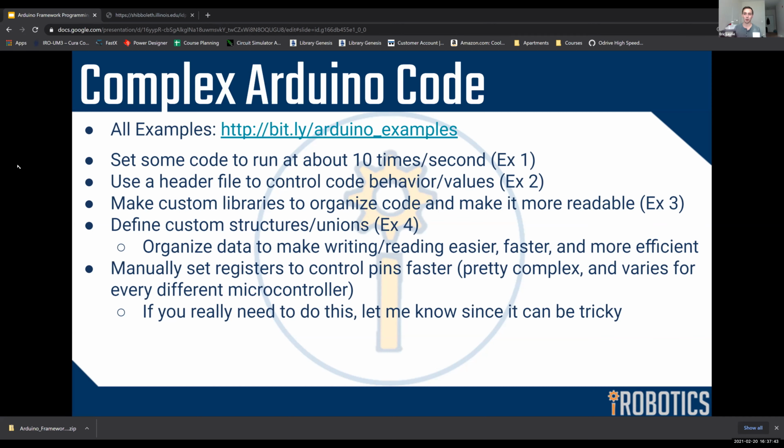They don't run at gigahertz like the CPU in your computer. Super fast ones run at like 400 megahertz. I think Arduinos run at like 8 megahertz; the Arduino Nano, Uno and Mega run really slowly. So the more things you can have happen slowly, the better off you'll be with putting in more code and more things your Arduino can do. So that's one way you can do that.